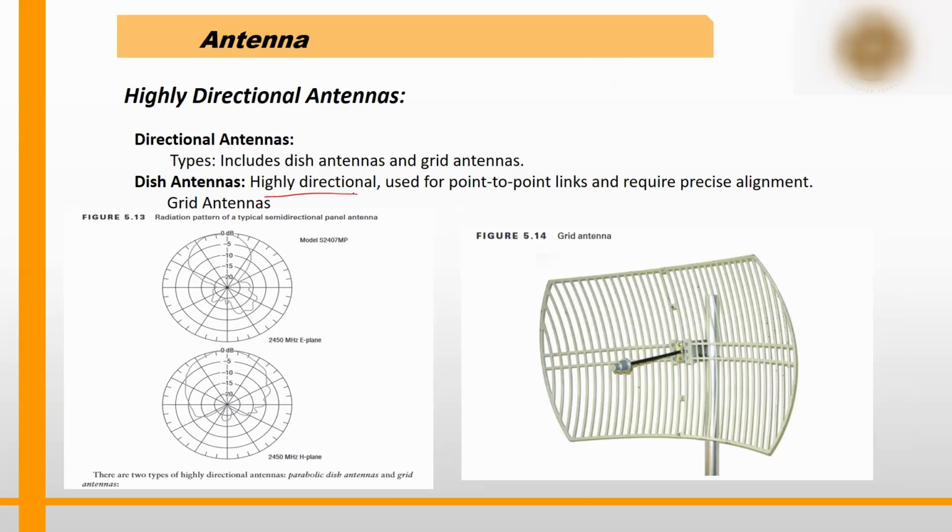And the dish antenna is highly directional. You can see it is a directional antenna, right? You can see the radiation in a single direction, but practically it will not be focused in an exact beam width like this. There will be smaller lobes in the other direction as well. Signal will be there, but they are weaker signals. Here you can see a highly directional antenna. The smaller lobe is there, but on the other side you have the complete radiation pattern like this. And why it is minus 20, minus 15, minus 10, minus 5, I have explained.